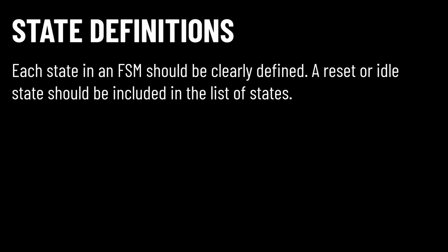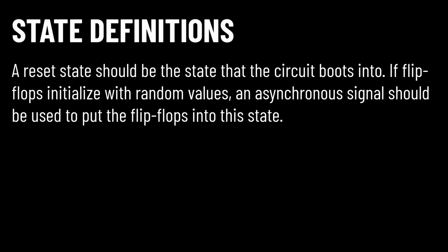Each of the states in a finite-state machine should be clearly defined. A reset state that corresponds to an idle or reset condition should be included in the list of states. Because flip-flops may initialize with random values, it's important to ensure that the reset state can be asynchronously entered by using the clear pins on each flip-flop. If using a flip-flop chip without asynchronous clear pins, then careful design needs to go into the circuit to ensure that a random initialization value won't cause the circuit to act in an undesired manner.